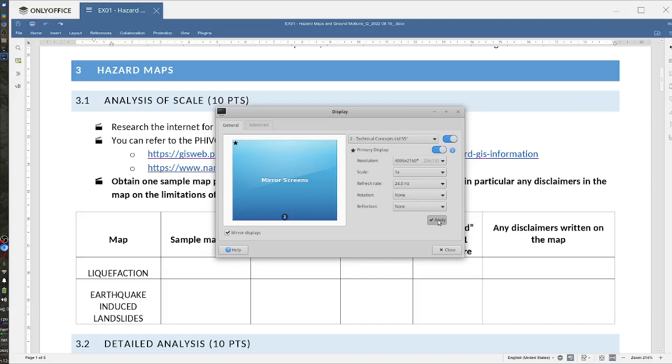But yeah, for general studies, Wells and Coppersmith is just a practical placeholder in place of the lack of studies. I think the one thing that's good with this one is that it has a big database of earthquakes. Though yeah, it doesn't include subduction earthquakes, so that's one big disclaimer.